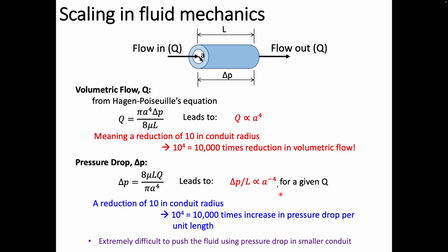So people typically don't use a pump, and what they typically use are different mechanisms, like capillary action. With the use of surface forces, they can drive the flow. Again, we are not even getting into a very small scale, just the micrometer scale, and because of this limitation, the pumps that you typically use at bulk scale cannot even be used. You have to use different mechanisms, because of this simple scaling law.